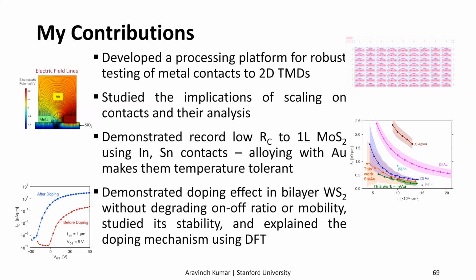Can I ask something? Yes, go ahead. Hi Kwan. Nice to meet you. I was very impressed with your research, and congratulations. I think your device is a backgated TFT. In this case, I think source and drain might be electrically doped. So if you use top gate, then how does the contact resistance change?